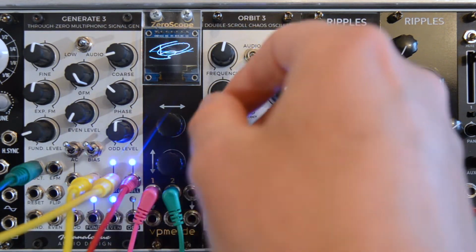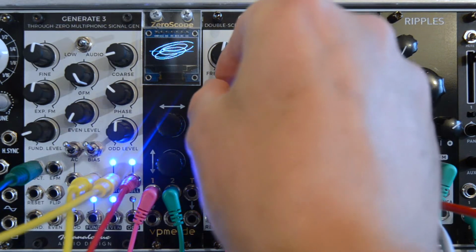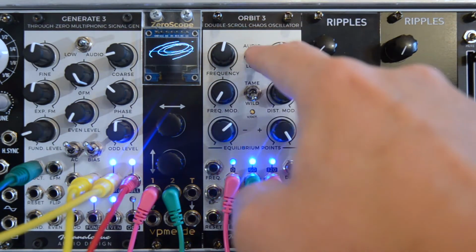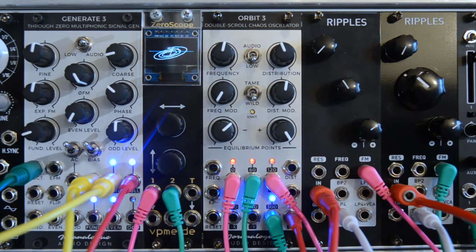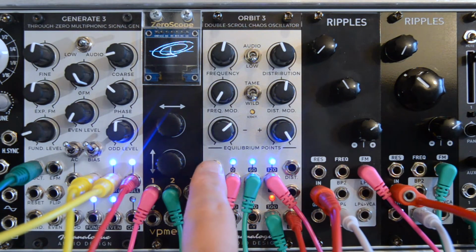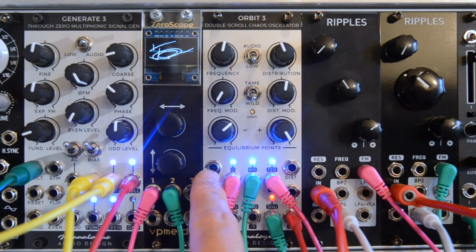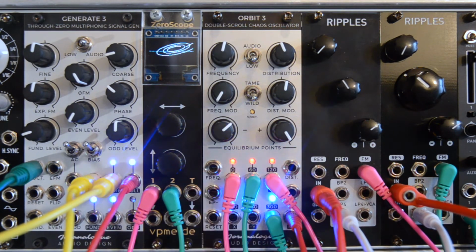The frequency modulation knob is a polarizer, so you can invert and attenuate the input. In low mode, the sensitivity of this exponential FM input is increased to 0.6 volts per octave. This is to ensure the complete modulation range can be achieved with input signals going from -5 to +5 volts without having to amplify them first.